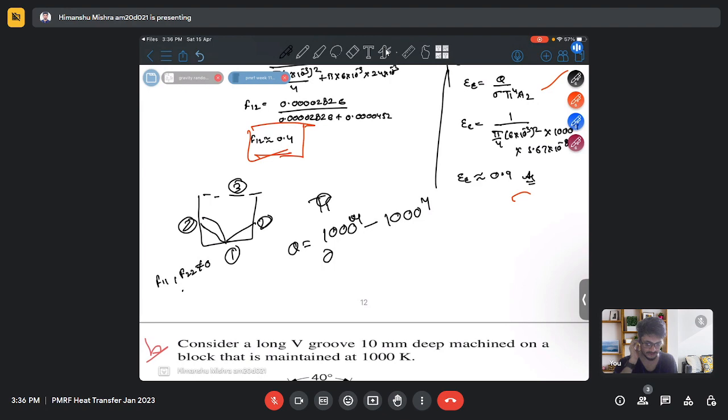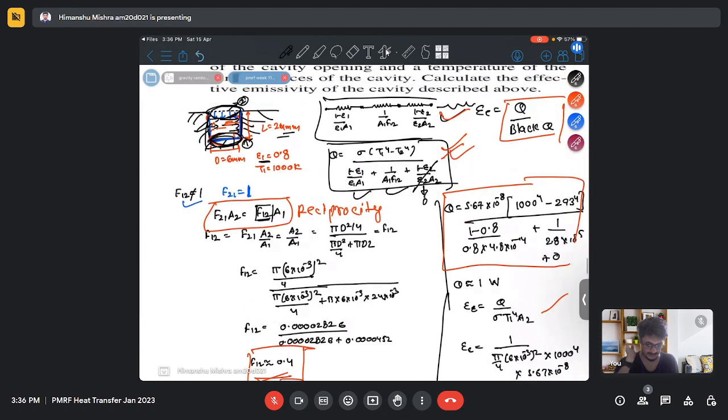So it is better to take the side and the bottom surface together because they are at the same temperature, then calculate the resistance, and then calculate the heat transfer between the remaining surfaces. It will simplify the problem, and we don't need to bother about multiple ways of heat transfer, because then we would have to consider different surfaces and heat transfer between the different surfaces.